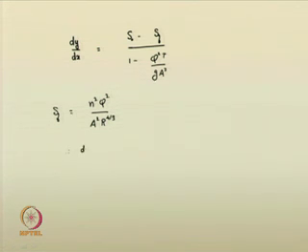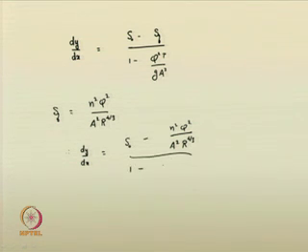So, therefore, your dy by dx is S 0 minus n squared q squared by a squared r to the power of 4 by 3, over 1 minus q squared t by g a q. You know that a, r, t, all these are functions of x and y for a non-prismatic channel. For a prismatic channel, they are functions of only y.